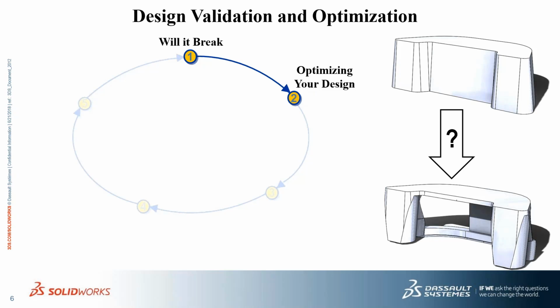So we're going to go back into SOLIDWORKS and look how we can copy our static study we just created, bringing all of the fixtures and load data over, and pull that into what is called a topology study, where we will add restraints and goals that the system will then iterate for us, and we will arrive at a nice streamlined part.